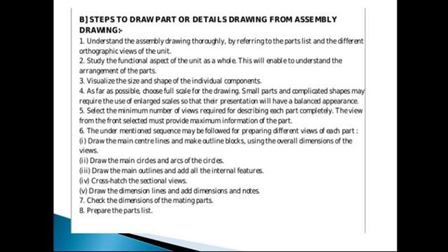So imagine that if one part is moving, then how the other part is moving, so that you will understand where you are able to dismantle the parts, because at the end we are going to draw a detail view. For drawing a detail view, we require to make a separate drawing of every part. When we are going to separate every part, it is required to first understand the movements. Once you understand the movements, it is very easy to locate every part separately.